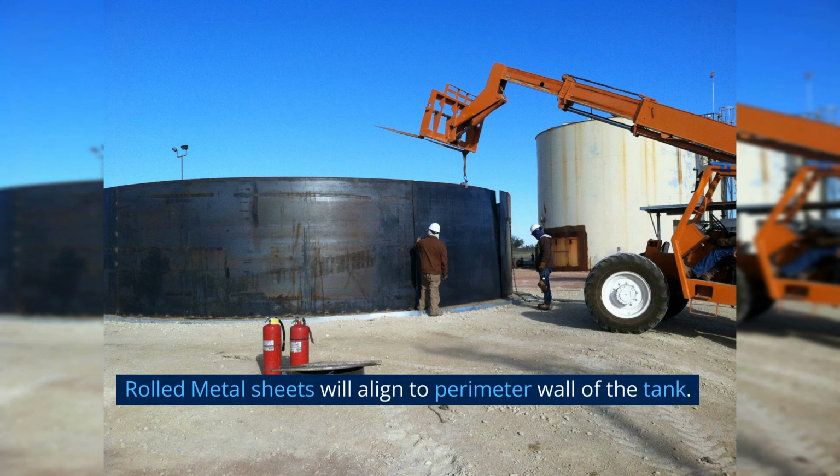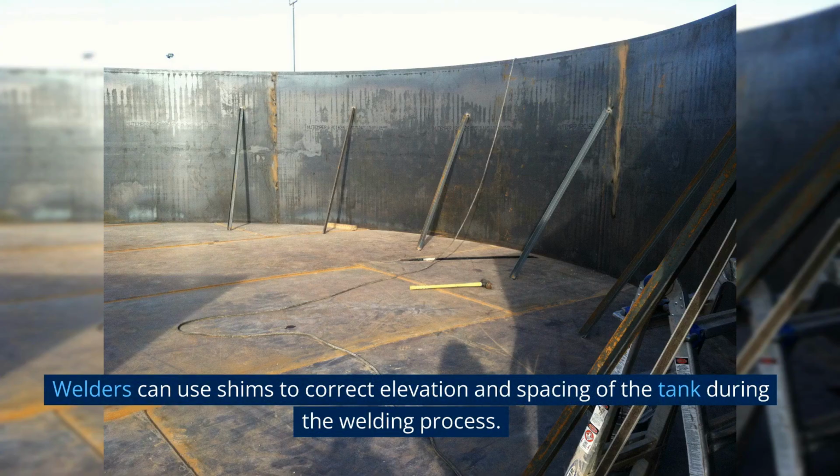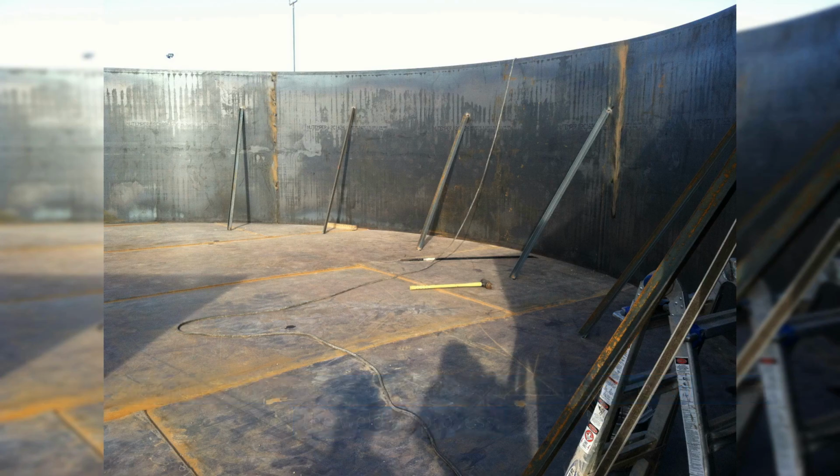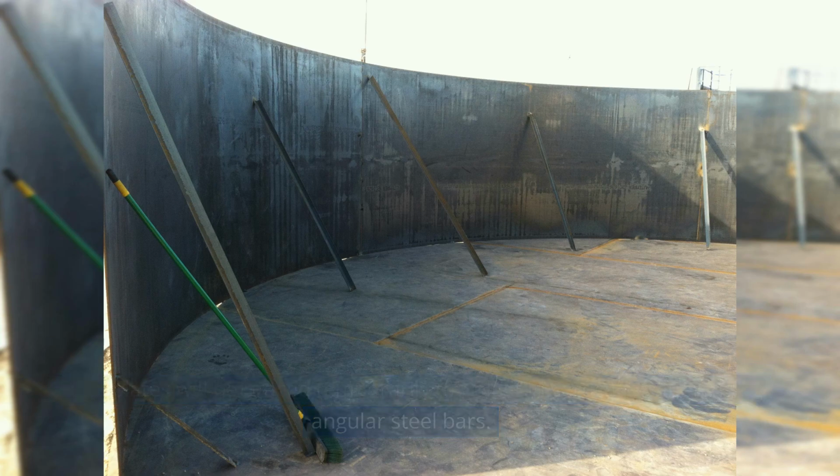Rolled metal sheets will align to the perimeter wall of the tank. Welders can use shims to correct elevation and spacing of the tank during the welding process. Steel plates will be braced temporarily to hold them in vertical position using angular steel bars.